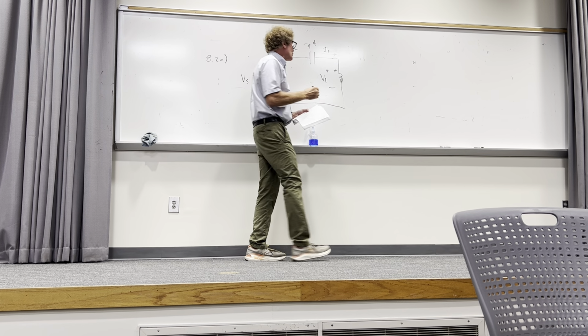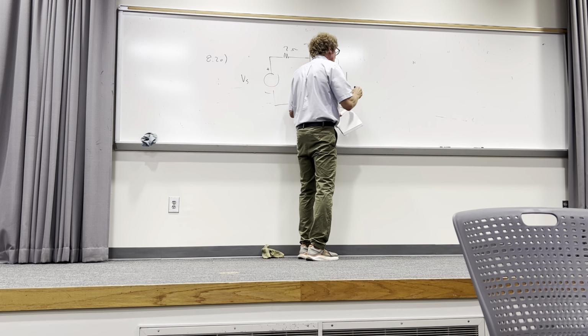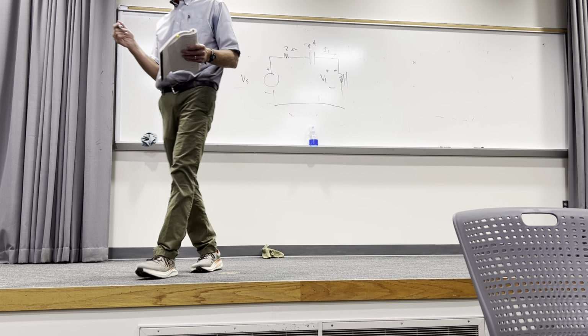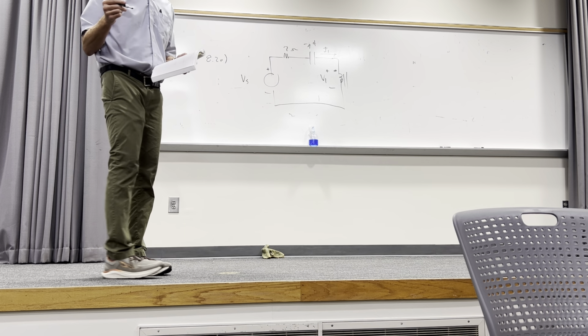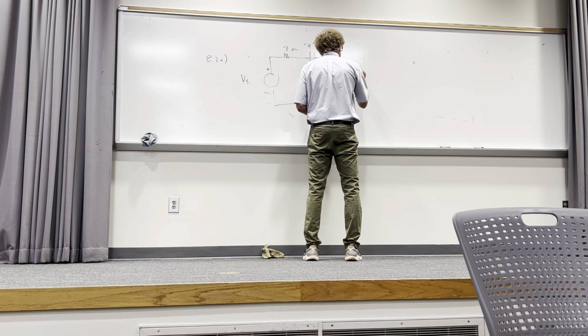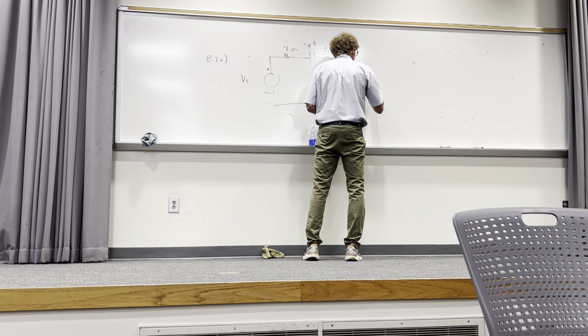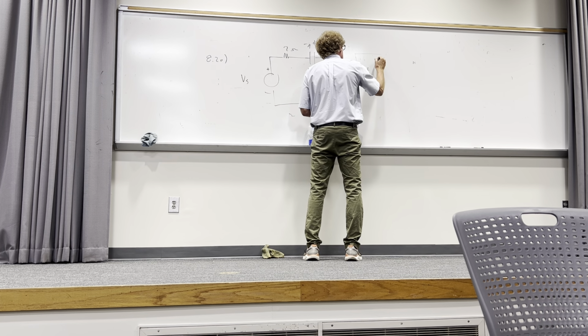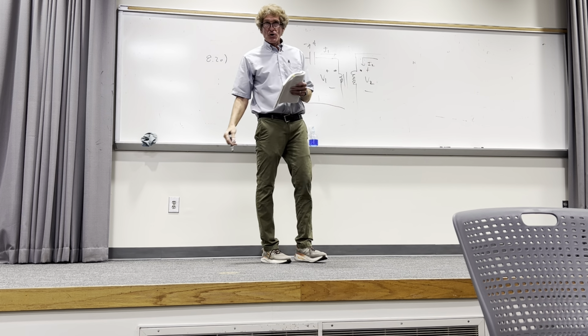Now these 2 straight lines indicate it is an iron core transformer. It's a heavy one, and it's for low frequency operation. That's all that means. Then you're going to have another set of coils over here. And you're going to have a dot there, and this will be V2. And this will be the current. Now the current always flows in to the terminal that is dotted.